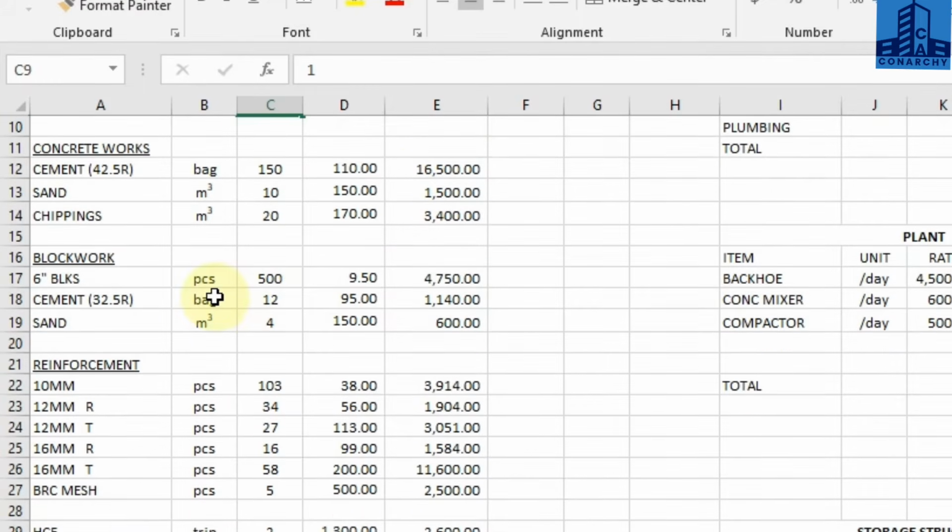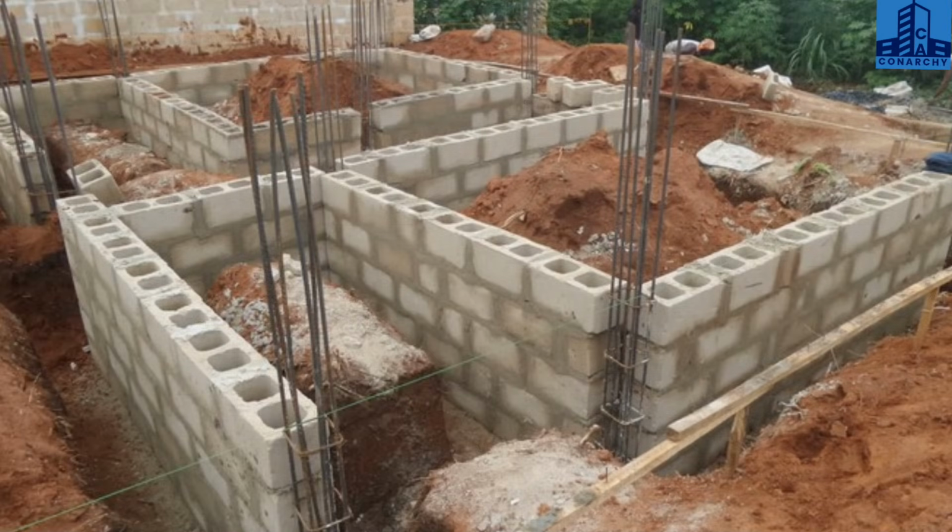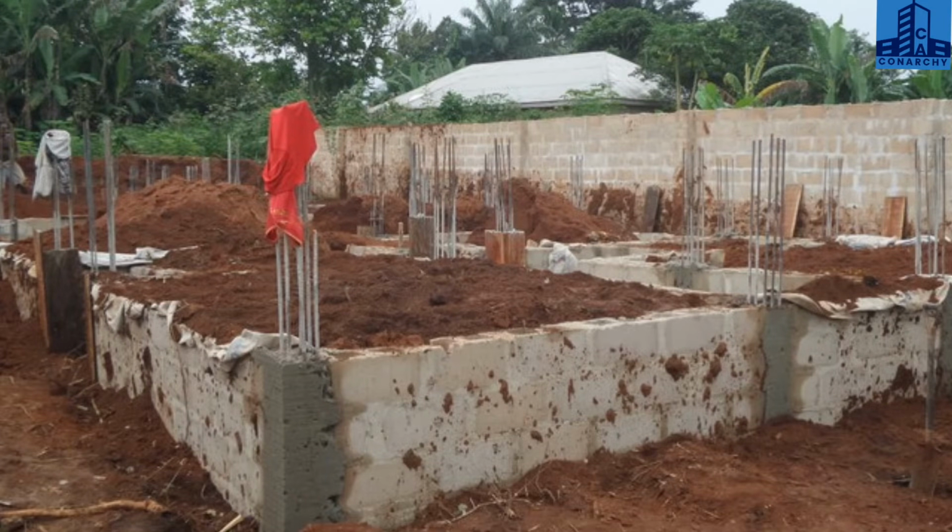And when it comes to the block works, you have to lay some blocks in the foundation. You have to raise it above the ground level, like around 2 courses or 3 courses above the ground level. This is to make sure that your building is above the road level, so that in case of excessive rain or flooding, which sometimes occurs in places like Accra, and not just Accra, the runoff water wouldn't penetrate or enter into your building. So your building must be higher.